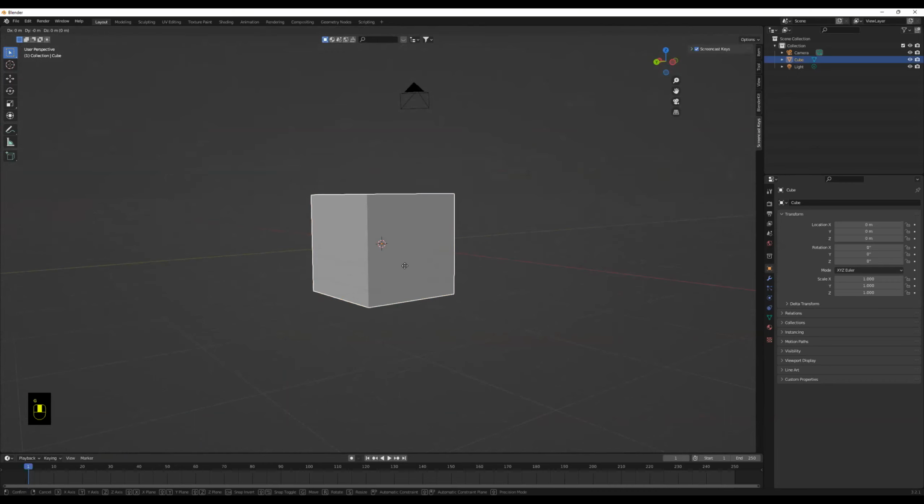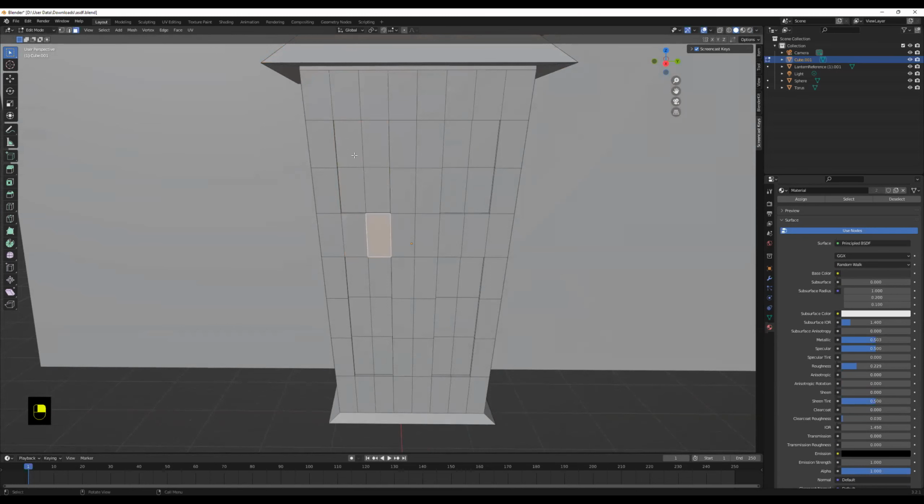So when you tab in and you have face select on, you can select different faces with shift right click, or left click, I mean. And then you're going to right click those selected faces and you can subdivide. Okay, so you do tab and then right click subdivide? Not the whole shape. You have to select the faces first by clicking on them. And then once you've subdivided, you're going to select all the different windows that you're going to need.